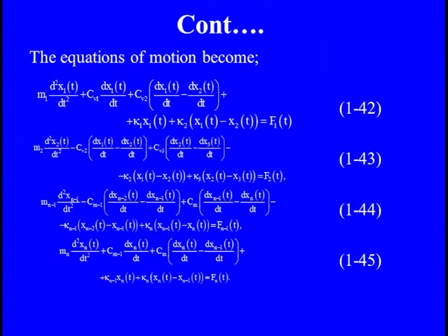If we combine all three, the input and output, then certainly we end up with our main solution matrices: minus omega square M plus i omega times the damping matrix, plus the stiffness matrix, times the x part, and then it is equated to whatever the force is which is being excited. Now our main theme here is to get the homogeneous solution.